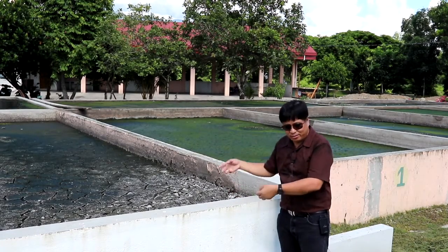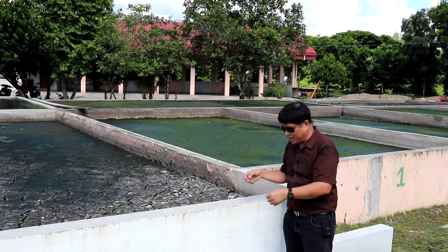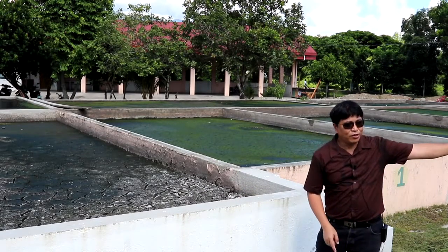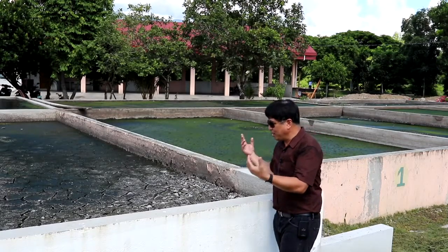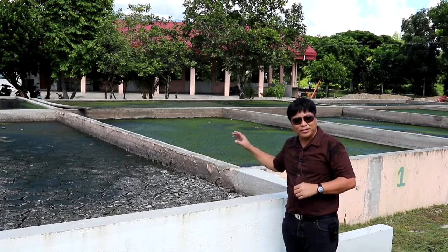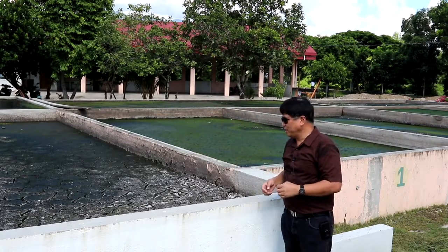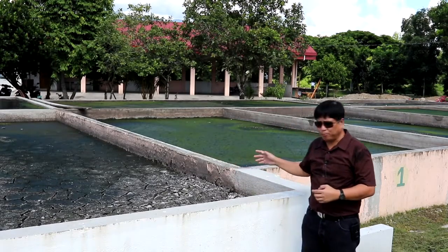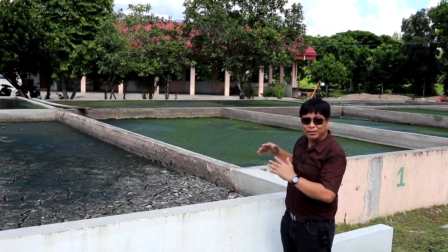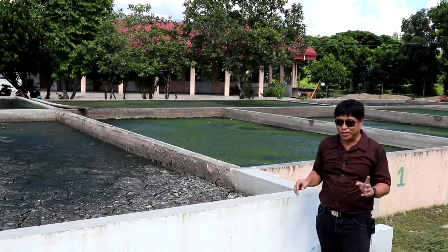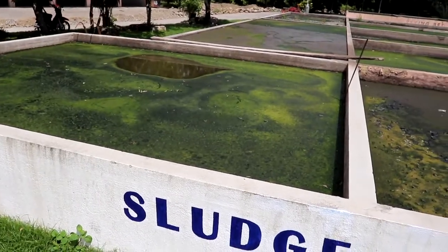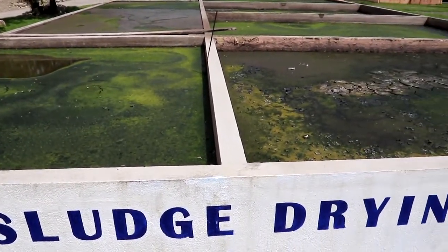So the filtrate, meaning the water that is part of the slurry, is sent back to the anaerobic pond, while the sludge is left to be dried using natural means, the sunshine. But for rainy places, we can put some transparent roofing so it will not be affected during rainy days. In tropical environments, it takes between 2 and 3 weeks to dewater sludge to the point that it can be removed by a shovel.